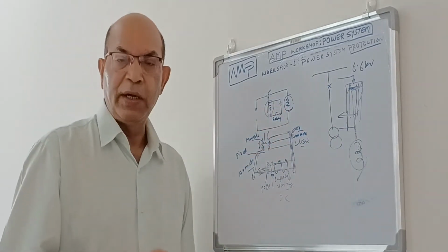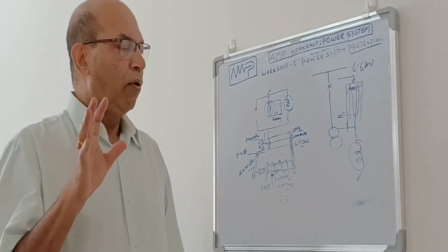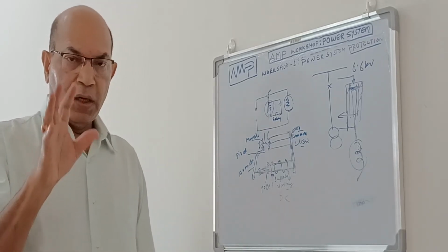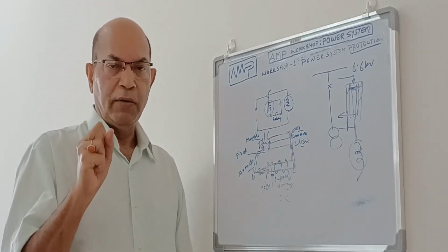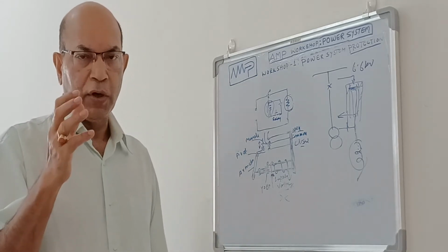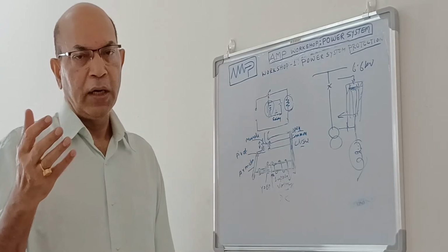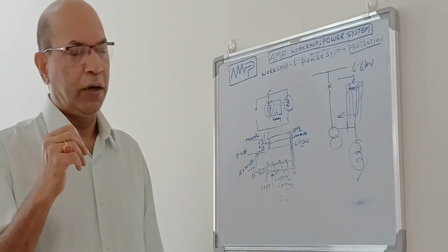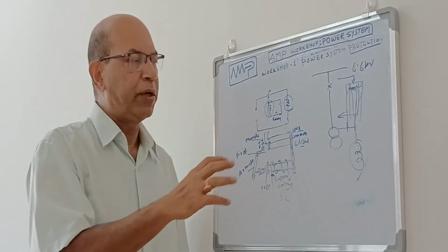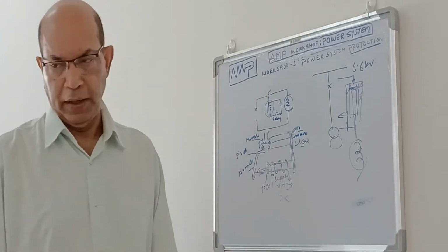So in brief, a relay is a control device. What it does is take a small control supply and give an output contact which can be used to open or close a breaker by using a solenoid, or a small motor, whatever is there. That is the purpose of the relay.